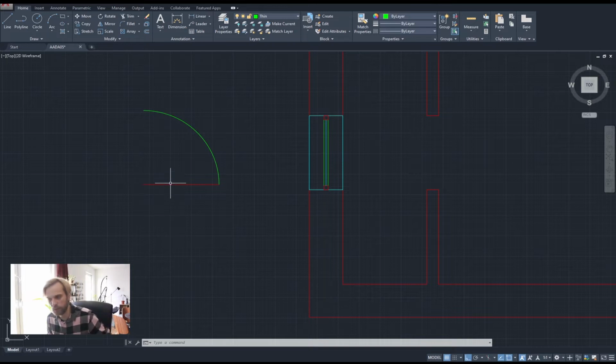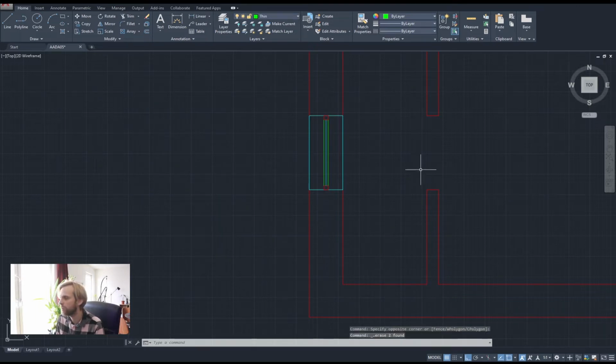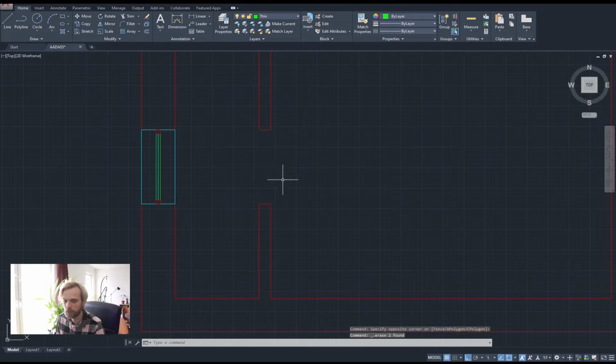The door is shown in a thick line because you're cutting through the door, and the opening of the door is shown in a thin line because it's a non-existing geometry, right? It's something that you just use as a markup to show the travel. So you don't even need to have a medium line for that. It needs to be a thin line. So that kind of doorway needs to be incorporated here.